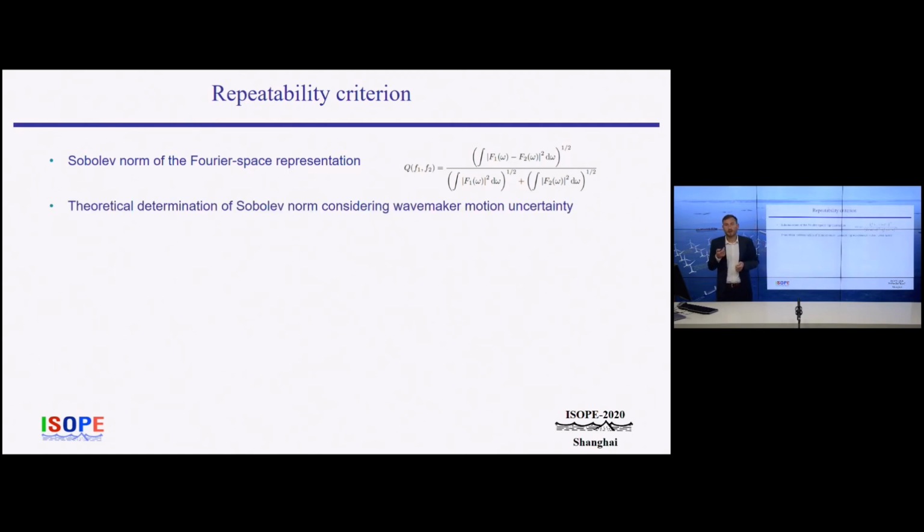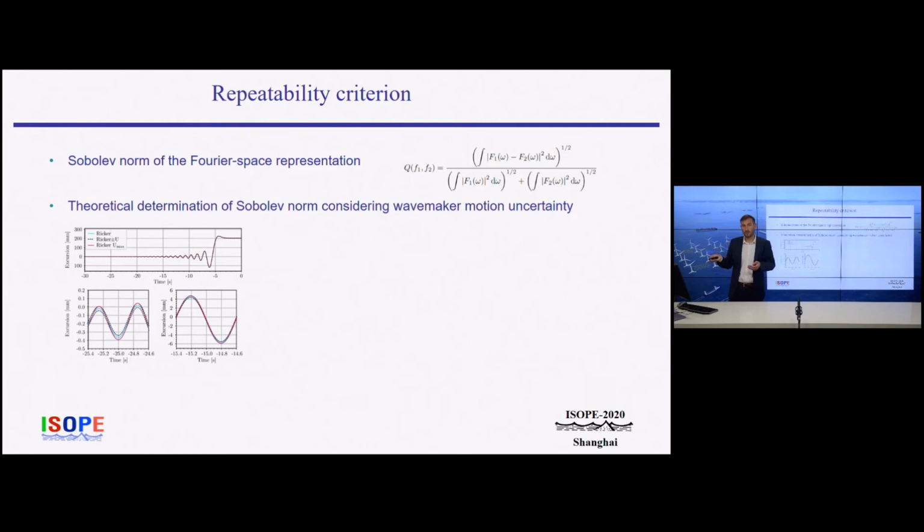The wavemaker is the most important element in wave generation and wave focusing, because it's far from the impacting wall. Considering the uncertainty in wavemaker motion, a value for the similarity parameter can be theoretically determined at different positions along the flume by simply propagating the control signal that accounts for the motion uncertainty to the intermediate position.